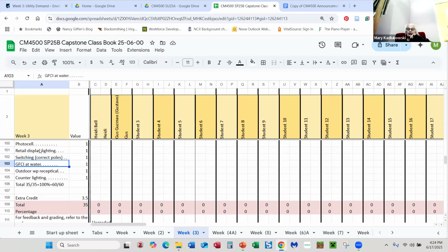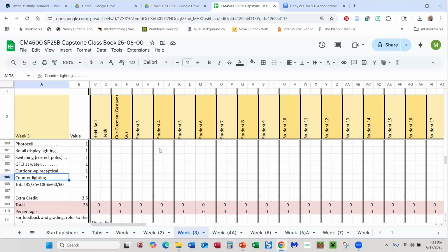Don't forget that if you put an outlet at blank height, it's generally at 18 inches, 12 or 18 inches as a default. So if you're putting outlets at countertops, like in the lab where you probably need a whole lot of outlets, and in that counter in the clinic, you want to give it a mounting height of like 42 inches off the floor. Otherwise, your electrician may mount all your outlets behind the cabinets. Oh yeah, seen that.